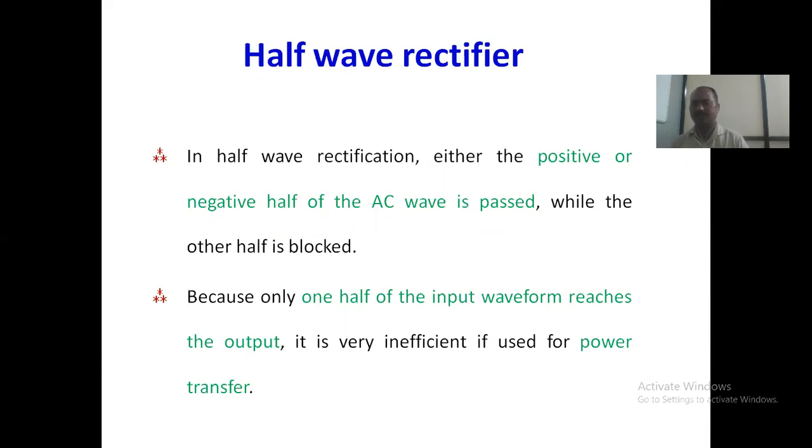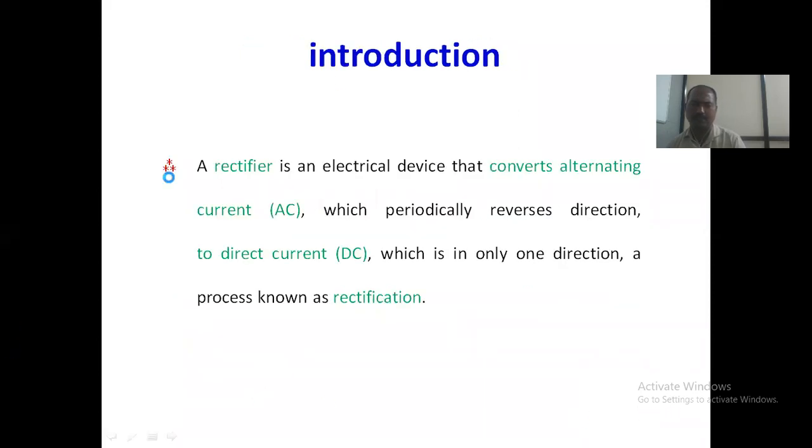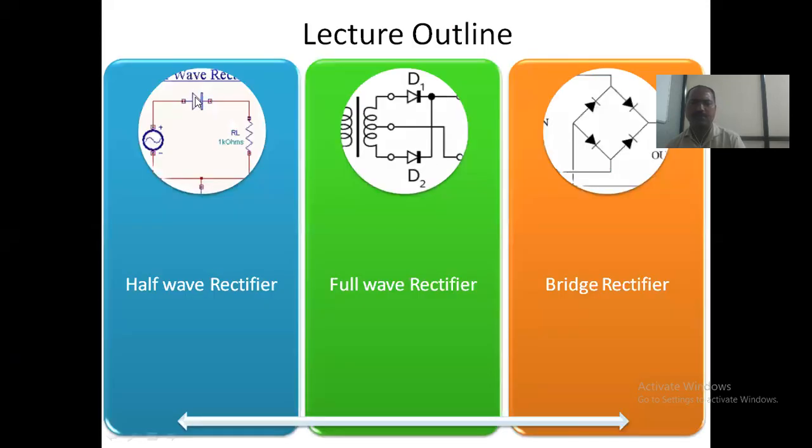See, the half wave rectifier is just introduced here because the time for it is less. A half wave rectifier converts either the positive or the negative half cycle. It does not only eliminate the negative half cycle; if we connect the diode the opposite way, it eliminates the positive part instead. See the diagram. This is the positive half wave rectifier, right? Only the positive half cycle comes at the output. If it is connected the opposite way, it is called a negative half wave rectifier, right? Whichever half cycle should be eliminated, the diode is connected the opposite way. That is the thing with respect to the half wave rectifier.